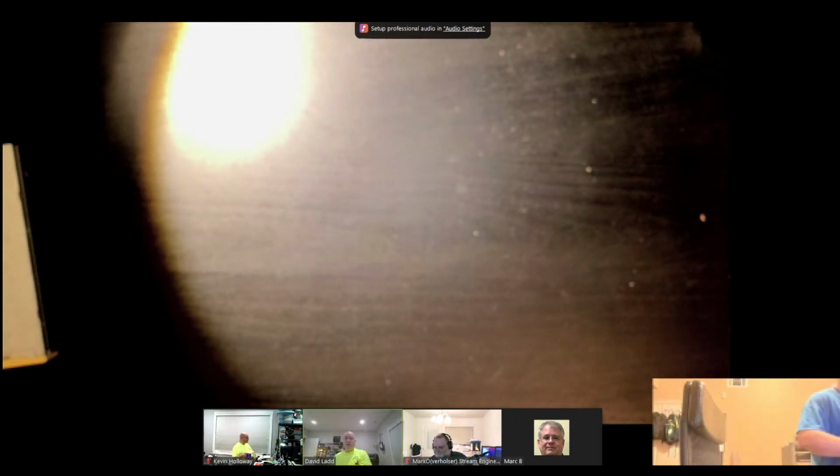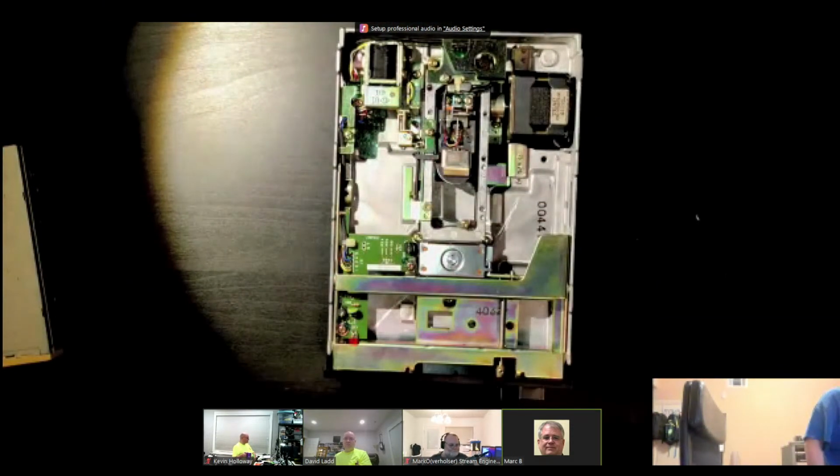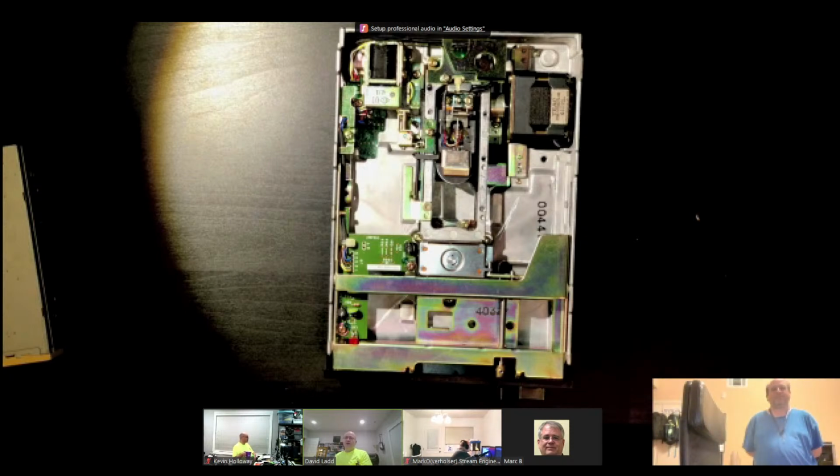Again, lubricants would be light sewing machine oil. How about gun oil? For lubricating, that would probably be okay. Another lubricant that leaves a film, which unfortunately would probably be a little too expensive, would be DeoxIT, because it leaves a film behind. The only drawback of lubricating that is it then starts attracting dirt and becomes sticky, so you'll have to do maintenance more often.